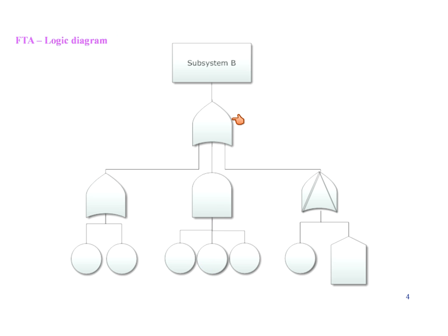We are just trying to find the previous event which has been the reason for the present event to occur. After finding this previous event, we try to find the event previous to this. So it's like a chain of flow of the events which cause the accident. So this is the general outline of how a fault tree looks.